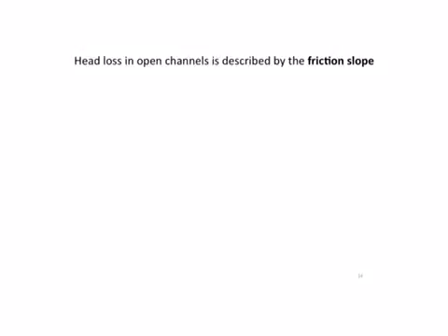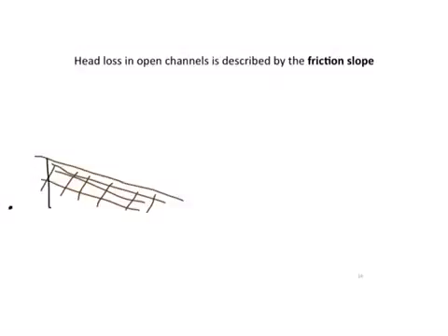And so to figure out how we deal with this, let's just go through a graphical depiction of what's happening as you move from an upstream location to a downstream location within a river. So this brown color here represents the riverbed. Rivers slope downstream, and we could actually represent the elevation head of the bed. Let's just say our datum is somewhere down here. So this is z equals 0. So this is our zb at point 1. We'd have a much lower zb at point 2.